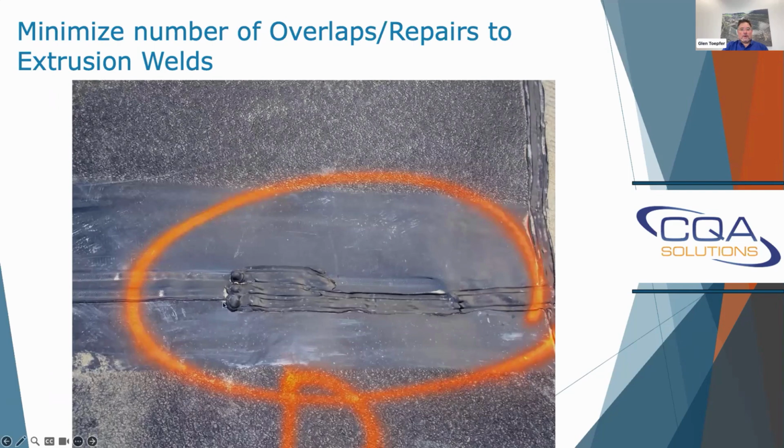This one here, same thing. It was a fusion weld. They did some topping here. It looks like for the T, they just ran it longer, removed the flap, but then they put another bead on it as well. So that can be cut out and patched and reduce the heat, get the heat away from the extrusion seam, except where it has to cross for the repair.